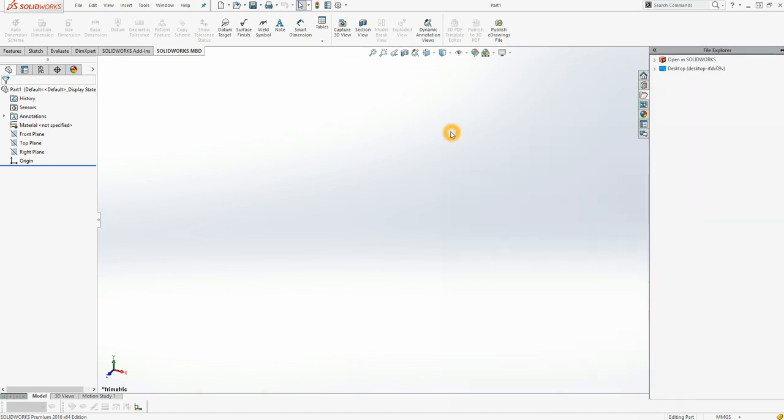Let's say you don't want to go outside SolidWorks and you want to explore something from here, you can do that. The fourth one is the view palette, which will not work on a 3D part like this one. Why? Because it's intended for converting a 3D part to a 2D drawing. That's why it cannot open up over here even if you click on it. The fifth one is the appearance. The same thing this button will do. You can use the task pane on the side over here also to perform that same action.